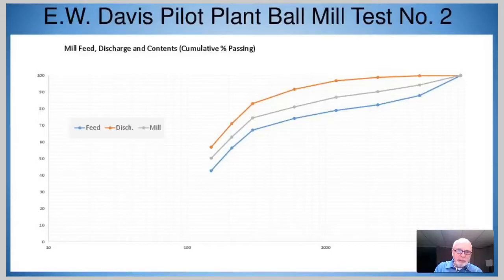This was a ball mill circuit set up in closed circuit, grinding to a P80 of, say, 150 microns, and with the classifier product being, say, 150 microns. And Professor Davis sampled the circuit and then crash stopped it, dumped the mill contents, and then actually did a size analysis of the entire mill contents.